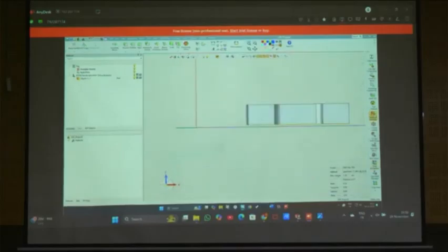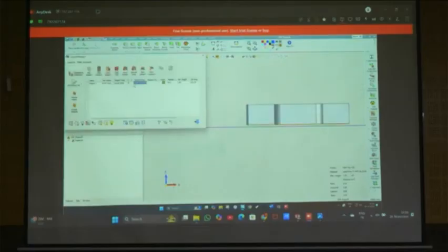So again support manager, see that is the reason we are getting here. See, we are getting the reason, right? So I can apply the support. If I am going with the wire cut EDM, I can apply the solid support so that I can remove it. But to reduce the post processing time of wire cut EDM, and to reduce the material, I can apply some other supports also, like wall type supports and all those things. First I will apply the solid, later we can see the other support.